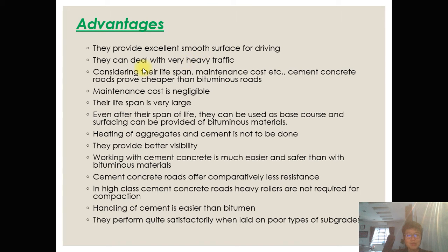It deals with heavy traffic; with concrete, no problem sustaining bigger loads. The lifespan is good because it requires very little maintenance, so the maintenance cost is negligible. Long lifespan, heating is not done, and so on. You can go through this. It says that handling of cement is easier than bitumen. In a way, that's true.